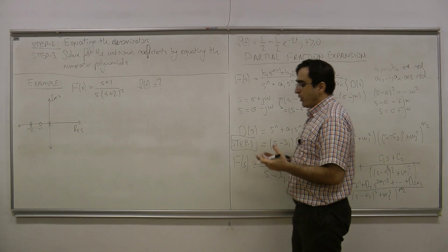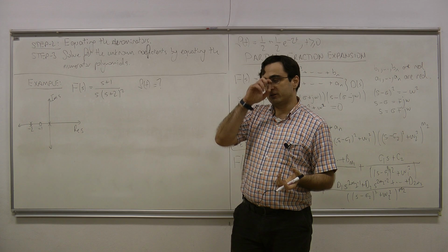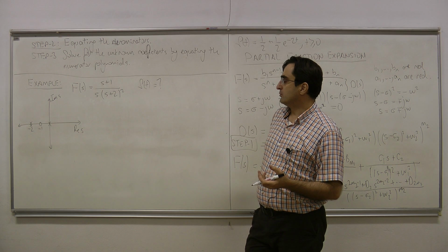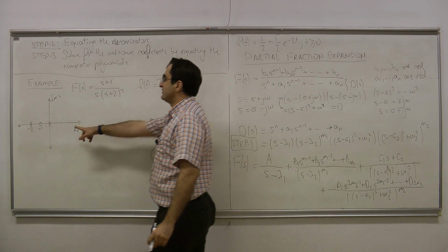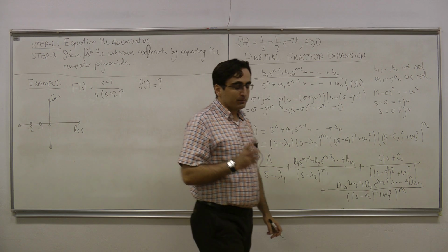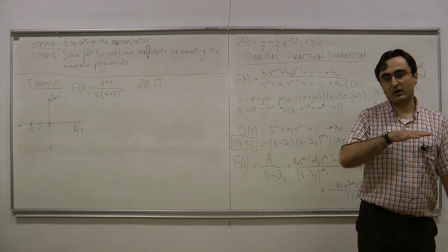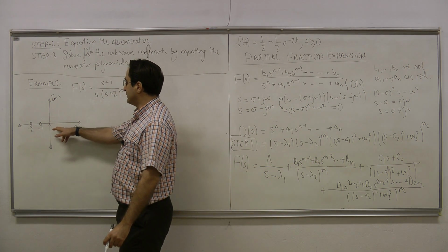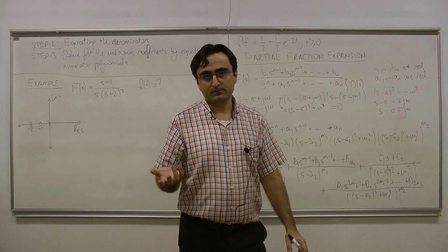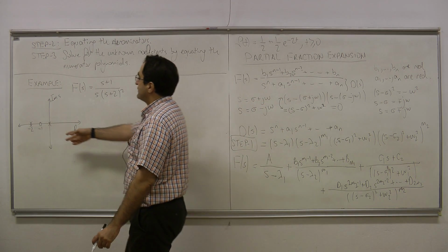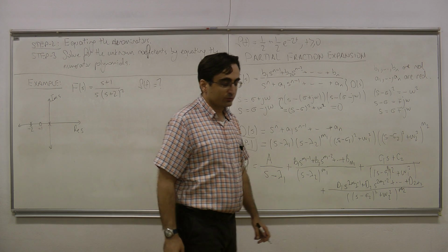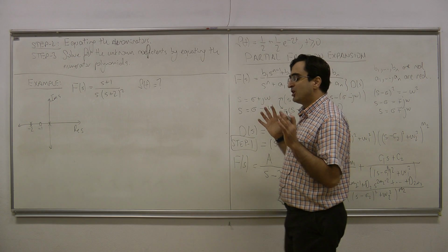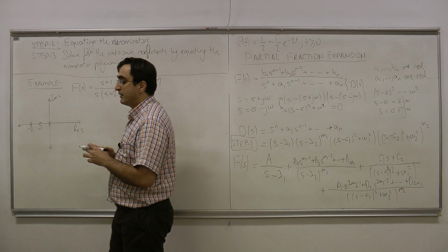If you watched the earlier lectures, you might remember what type of time functions we would get for this case. A single pole at 0 is going to mean a constant in the time domain, and it's 1 over s in the Laplace domain. Okay? And double poles at s equals minus 2, what would they represent? Remember the properties of the Laplace transformation that we have seen.